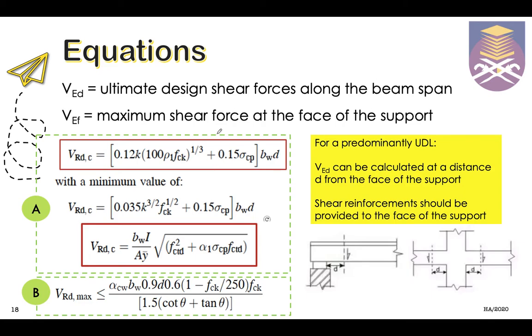So we have VED, and also we have VEF. So usually this maximum shear force is considered at the face of the support. However, in the design of predominantly UDL, whereas we have a normal UDL on our beam, VED can be calculated at a distance D from the face of the support.